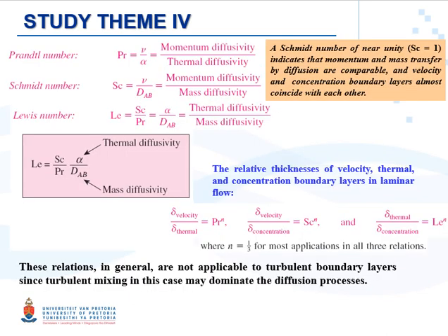So we talked about the Prandtl number, and we talked about Schmidt as well. But to present the relative magnitude of heat and mass diffusion in the thermal and concentration boundary layers, Lewis defined another dimensionless number called the Lewis number, as you can see here, and it is defined as thermal diffusivity divided by mass diffusivity.